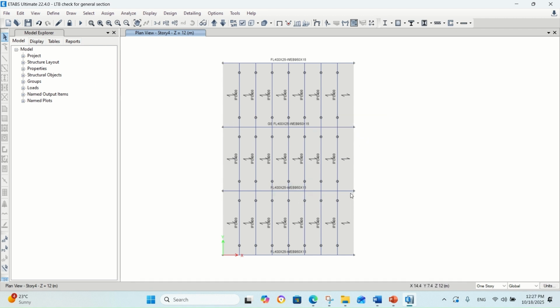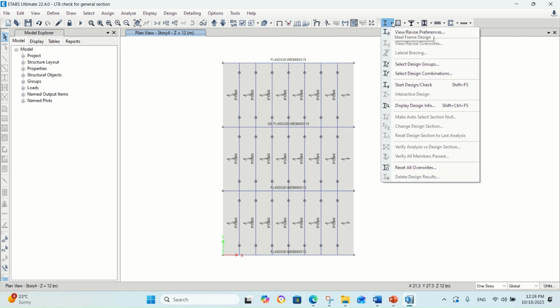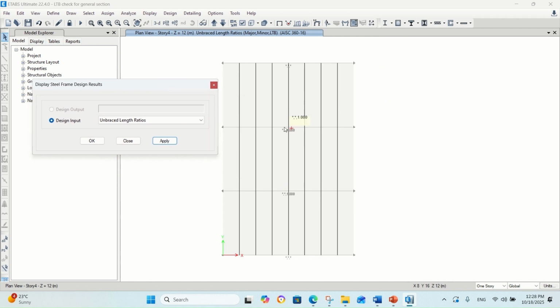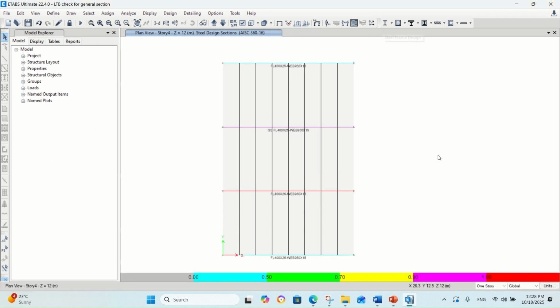However, here we want to show the differences, especially if we have a case where the lateral torsional buckling is the full length of the member or we don't have braces against LTB. So let's see. Now we have LTB is 1, the third number. The first two numbers are automatically calculated by the software. So now we will run.